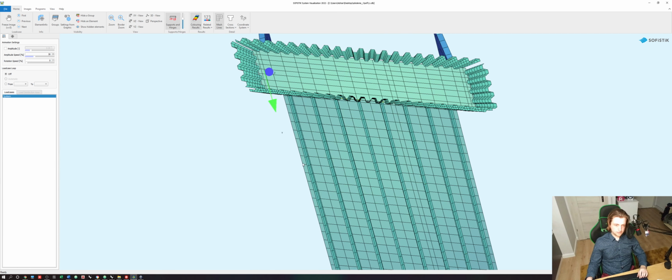usually I use the single partition, and somewhere between our first part which will be created and the second part which will be created in the next phase, we want to have some small gap which we have already defined in our model, but only we have to move those points at the level or the elevation of the middle of the concrete deck plate.